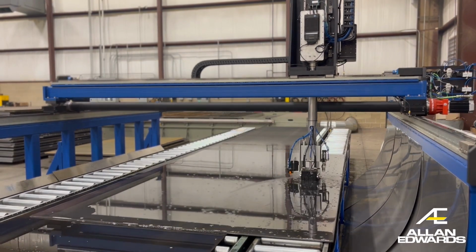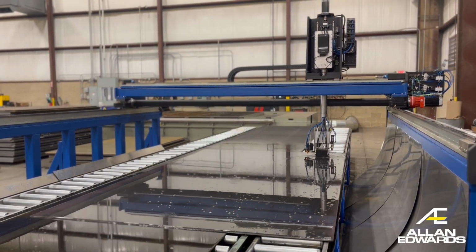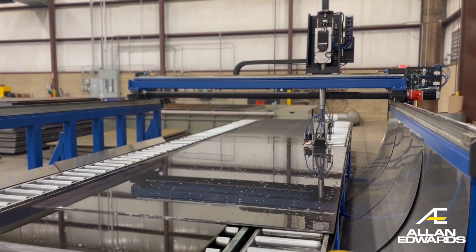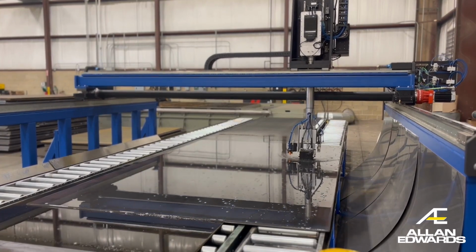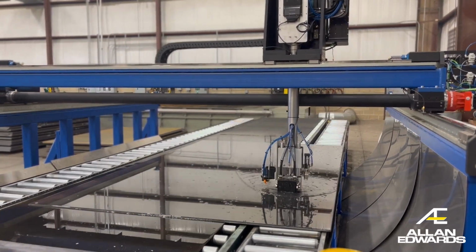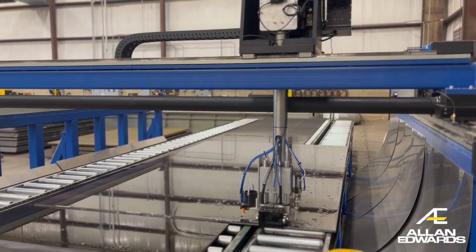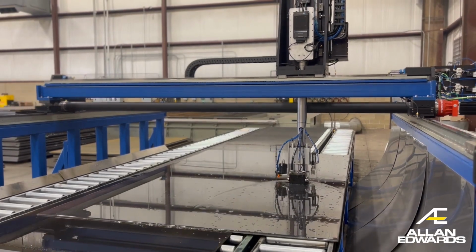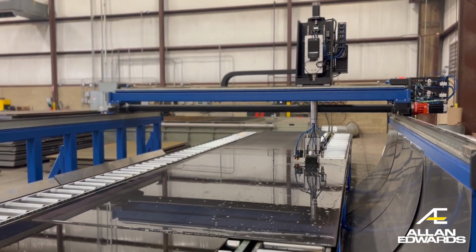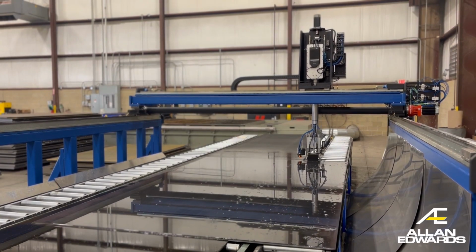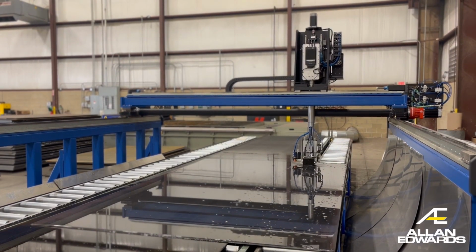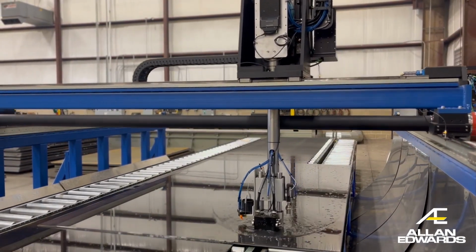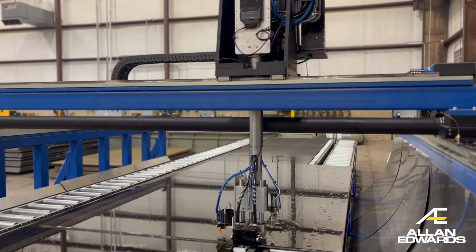So this is showing a little bit of video of the machine scanning the plate. So it's got a water bath. It does a 10% overlap. This is real speed. So it scans a plate in approximately about 4 minutes. As the machine feeds the plate in, it does edge detection to not only align the C-scan to the plate, but make sure it does UT thicknesses, so it pulls the right calibration for the machine.